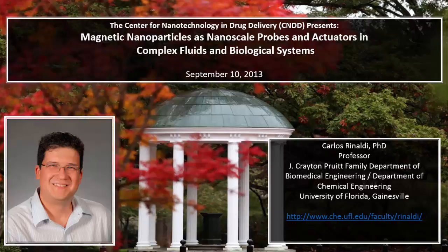We measured the susceptibility curves. We estimated the size in water. We fit the susceptibility curves, and we determined the viscosity. And this is what we get. This is molecular weight of the polymer, viscosity on the y-axis. Again, it's logarithmic. Three different temperatures. The closed symbols are the viscosities measured using a rheometer. The open symbols are the viscosities measured using the rotation of the particles.